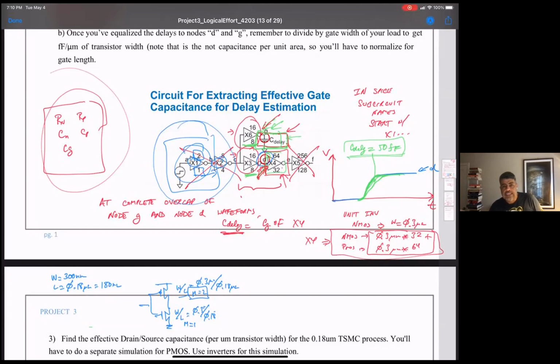And so on and so forth. Yeah, I think that's the great thing about Spice, paralleling stuff. If it's easy to pass the parameters, I would go with that route and use the M factors. I keep forgetting, I don't use LTSpice enough to remember from semester to semester how easy it is to deal with the M factors. But I would go that route, and there's less possibility for some second order effect that might confuse your calculations. If you just make the sizes, it's not going to be any points off or anything. I just think it'll be cleaner that way.